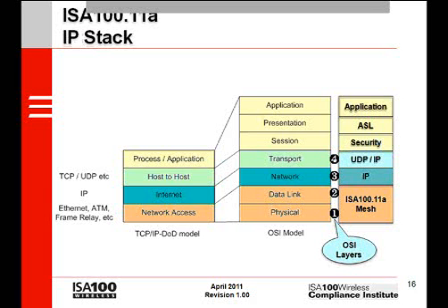In summary, when we say that ISA100 uses IP, that means that it uses network and transport as standardized by the Internet Engineering Task Force, or IETF. The special wireless mesh capability, optimized for field device operations, is added below IP in layer 2. Above UDP in layer 5 is the session layer. Application services are in layer 7, also above UDP. ISA100 is literally an extension of IP.